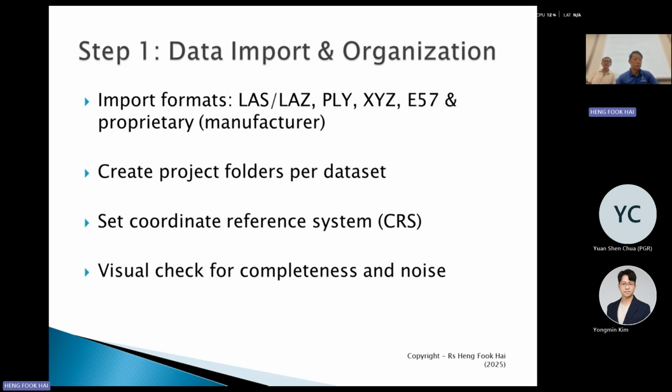The first step is, of course, after you capture with all the instruments, you have to import the formats into the software, creating these project folders. And of course, you also need to do the coordinate system referencing to make sure that it goes back into your actual local grid.